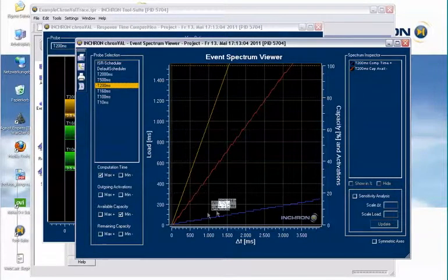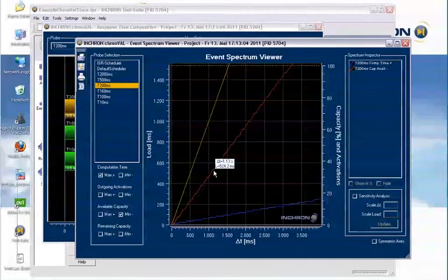So whenever we see a vertical gap here, we see that the 200 millisecond task could use way more computation power, so there's still some air here. So you could, for example, add more functionality into the 200 millisecond task. There would still be enough computation time remaining to complete this. But that might be a problem for the lower priority tasks like the 2000 or 500 millisecond task here.